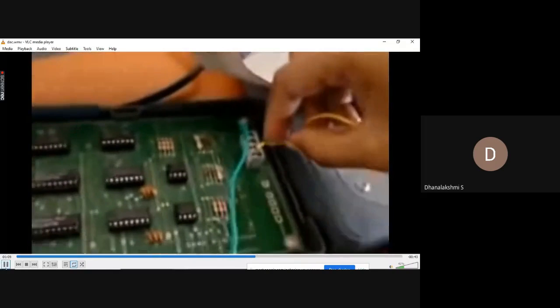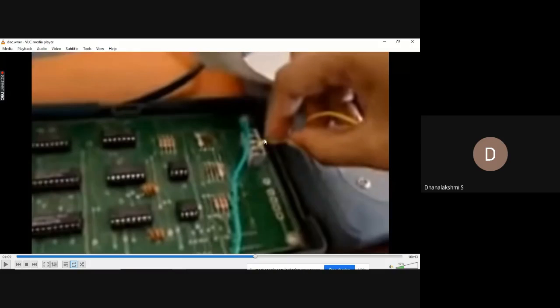Now you can see the interfacing board over here. I'll pause the video. So your interfacing board has 4 ports. The first one is FFC8, the second port is FFC0, and your fourth port will be ground. In your probe, you will have two ends, right? So the positive end should be given to either FFC8 or FFC0 depending on your code.